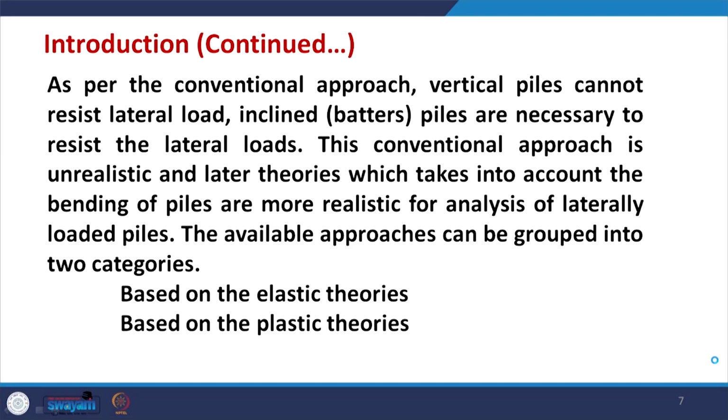Let me explain why it is unrealistic. This is similar to what you can consider like a column. A column that is free is not supported by the soil, but a pile is not free, it is supported. Even if you have a vertical pile, it will still be able to carry some lateral load.